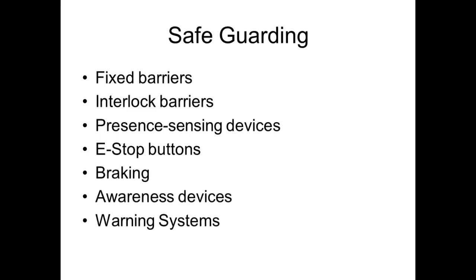If you hit the E-stop, then the robot is on brake. We don't like using E-stop, because robots, when they brake, especially that big one, we'll go over there and look at the brake pack on it. It's got all that inertia built up in it, right? Anything that's in motion wants to do what? Yeah, it wants to continue.